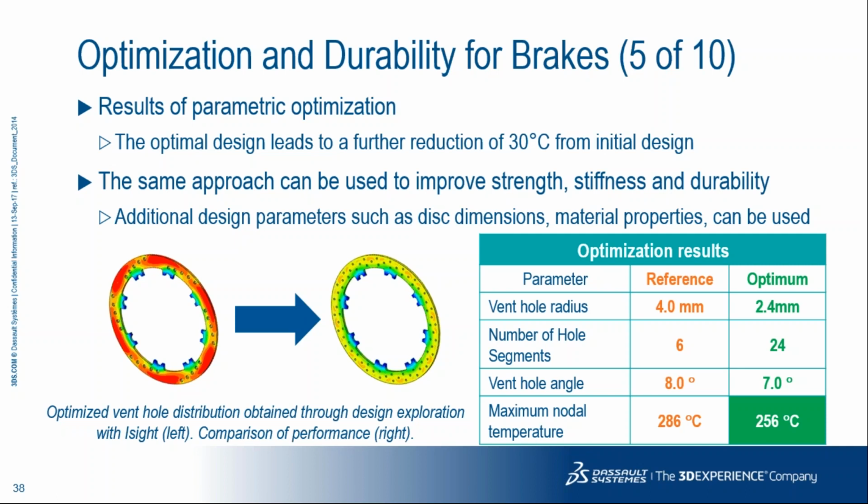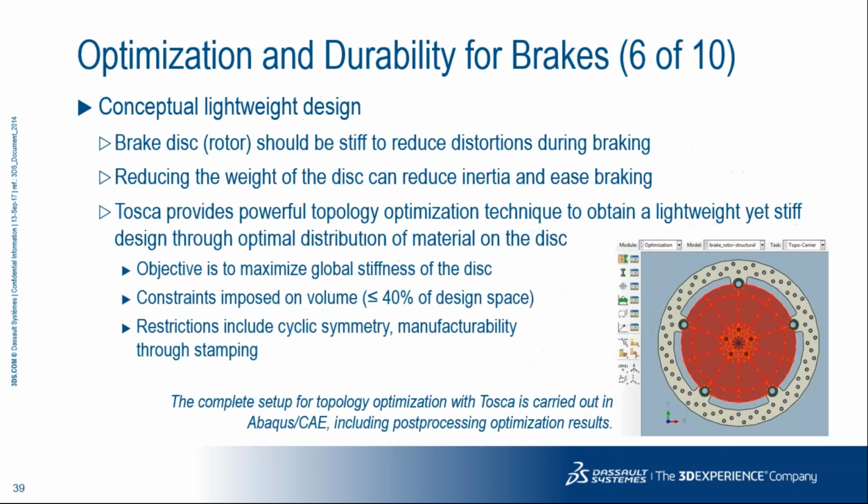It has been displayed. And in terms of conceptual lightweight design, here topology optimization is incorporated. Topology optimization allows us to determine the location and shape of the spokes, which is carried out to take the severe loads during the brake events. This is achieved by starting with a generic design space and removing material from structurally unimportant locations. The non-parametric approach allows basically any shape to be generated, thus finding a design that precisely reflects the functionality of the part, taking into account the exact conditions under which it operates.